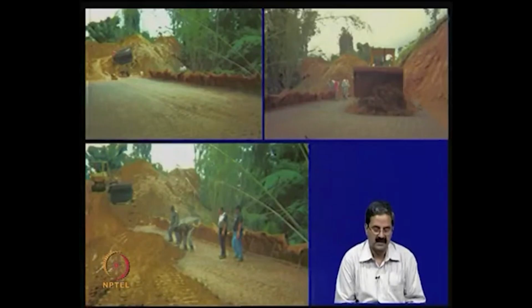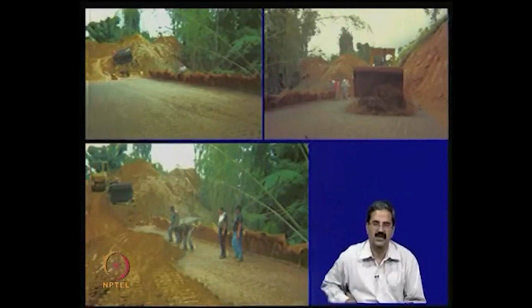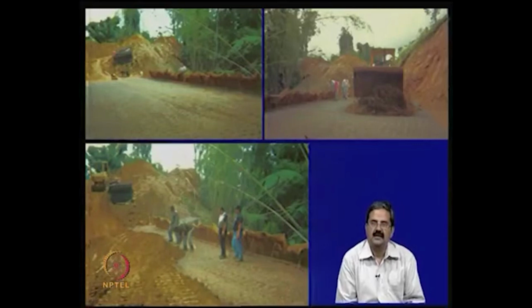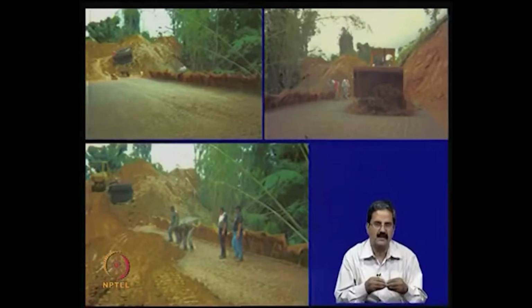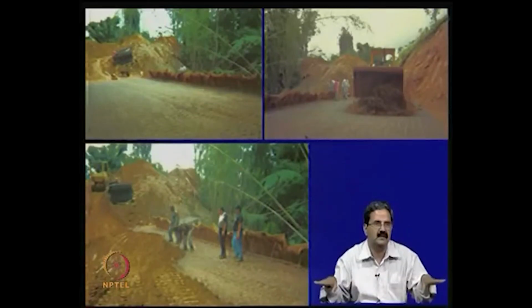It should have good density because the objective is that it should have very good friction between the soil and reinforcement, and there should be very good drainage actually, because what I just showed you was that drainage is very important. I gave you the slope design for r_u equal to 0, where the pore pressure coefficient is 0, but if there are seepage pressures or some horizontal force, like earthquake force, the length of the reinforcement will be high.